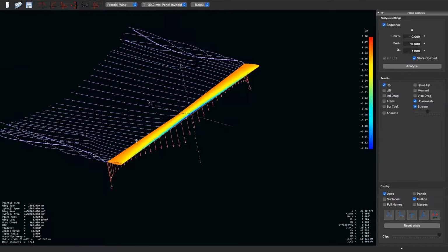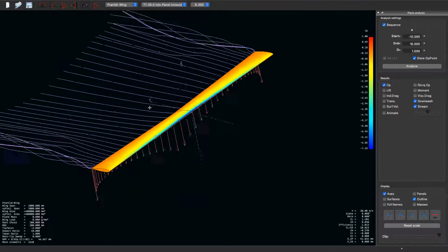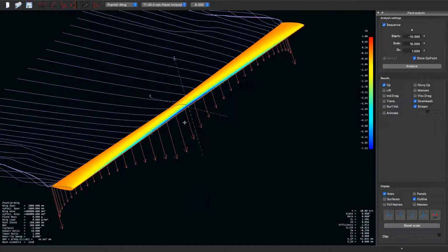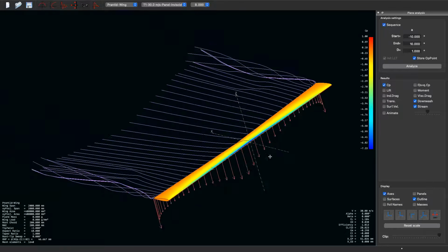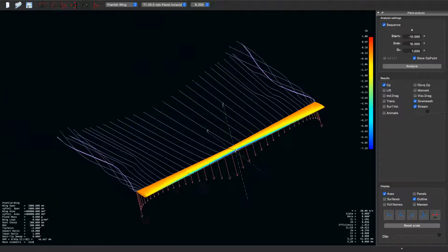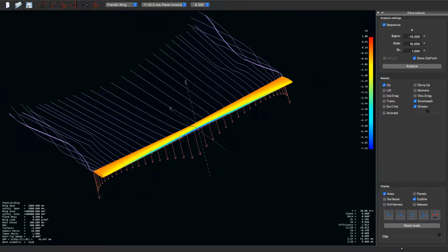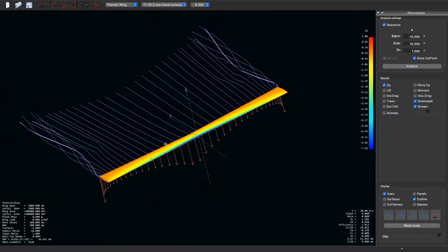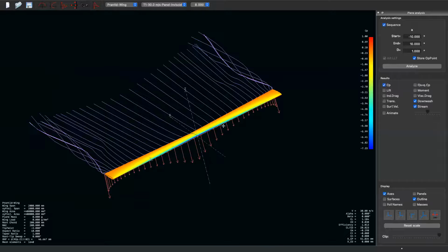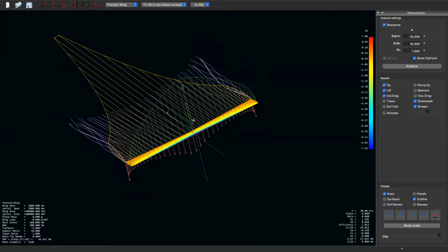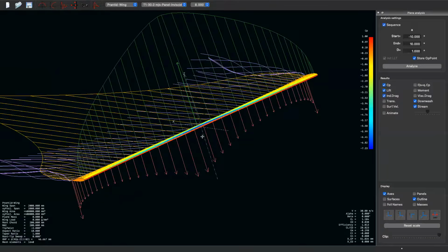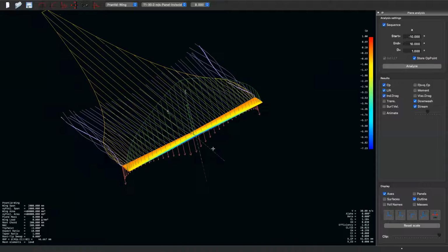You can essentially get any force distribution, any lift distribution you want on top of a wing by changing the twist. Now, this is all inviscid, right? I mean, if you turn on viscous analysis, there may be some separations going on. We're not accounting for that. But even from a pure understanding standpoint, I think this is a pretty good tool to allow you to visualize what's really happening and the relationship between all of these different parameters. That's very important in a finite wing.